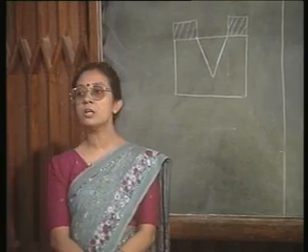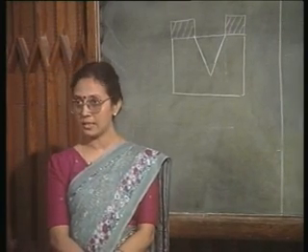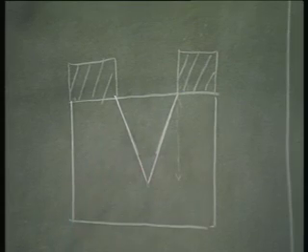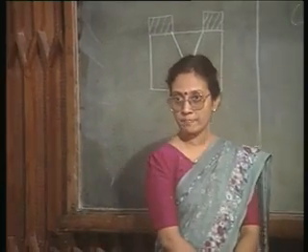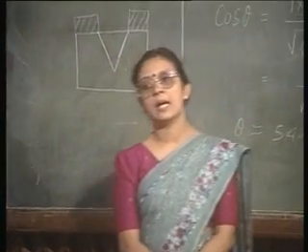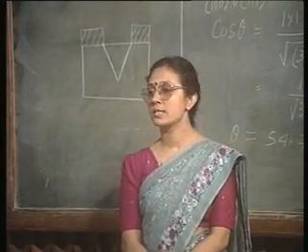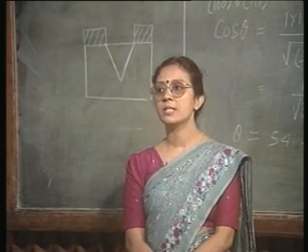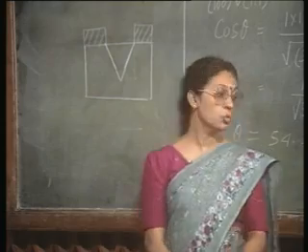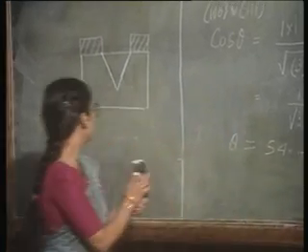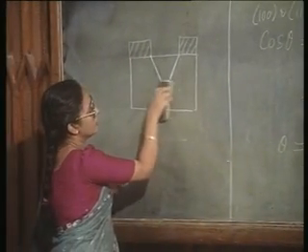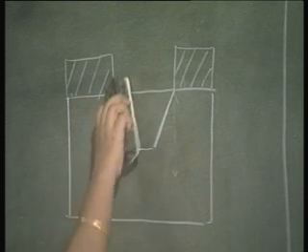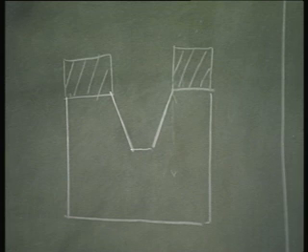Incidentally, this is called a V groove etching. The name is self explanatory. You are making a V groove in a 100 wafer. So, this V groove etching has various interesting applications. One such application is a device called a VMOS or a UMOS. Very briefly let me tell you what that is. For that UMOS you have a structure like this. You have etched it down and you have a structure like this.